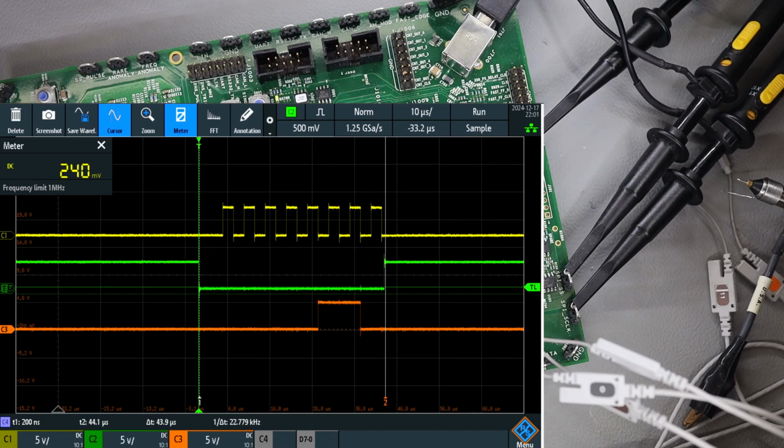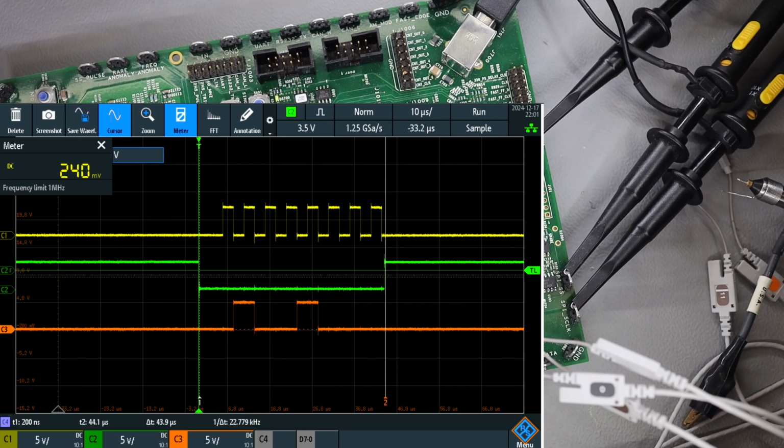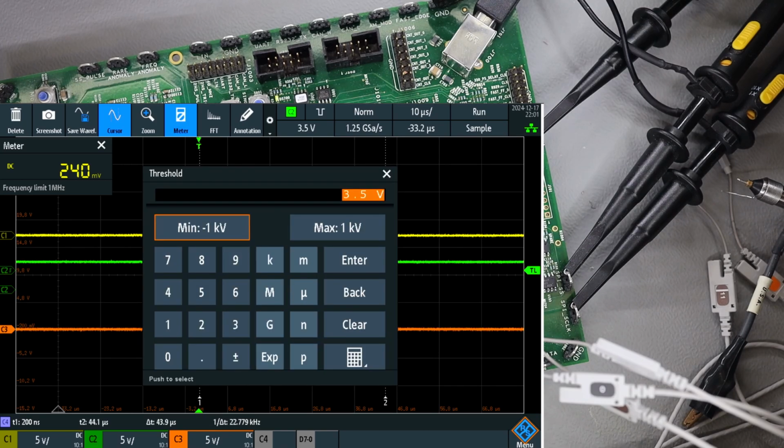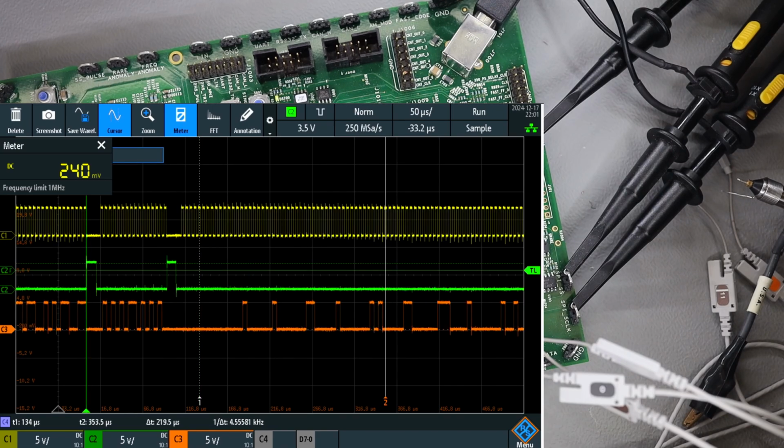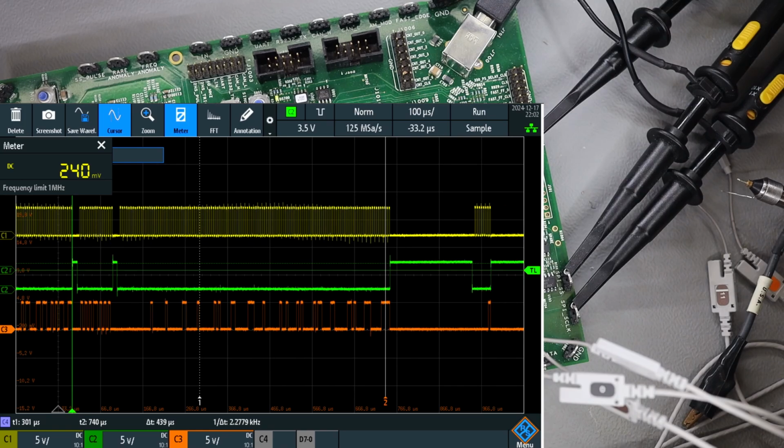Right now the trigger level is pretty low, so it will give you erroneous results. We are triggering on a positive going pulse greater than 50, but you see this is a negative going pulse, so I made a mistake. I'll go and change this to low going. So now, magically, we are capturing that packet which was rarely getting repeated.